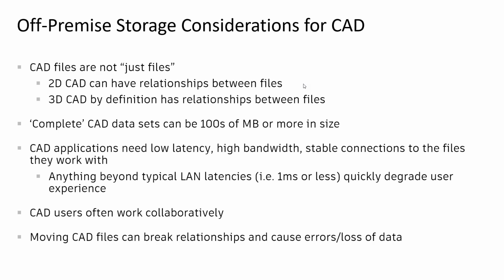Even 2D CAD like AutoCAD can get complex when you're managing files. You have XREFs, right? You may have linked spreadsheets for data. And if you get into 3D parametric CAD, again like Inventor, by definition you're going to have lots of different files involved, and those files all have relationships. And if you're missing a file that, say, an assembly or a drawing needs to fully work, you can't work on that assembly, right? So it's more than just copy the files to some share and work on them, and then you're done.